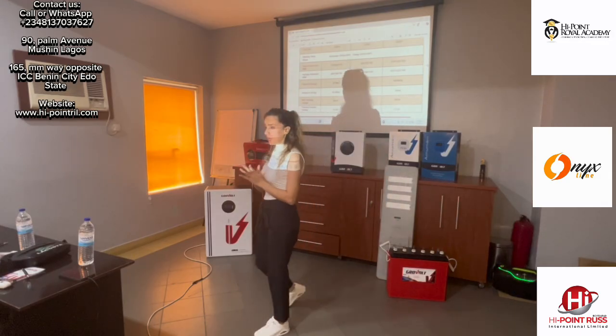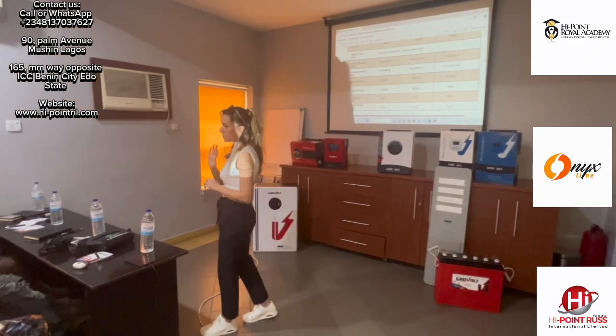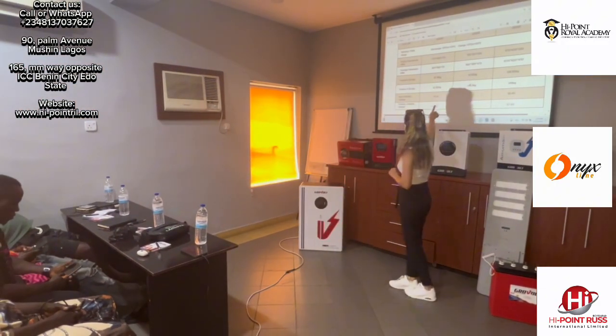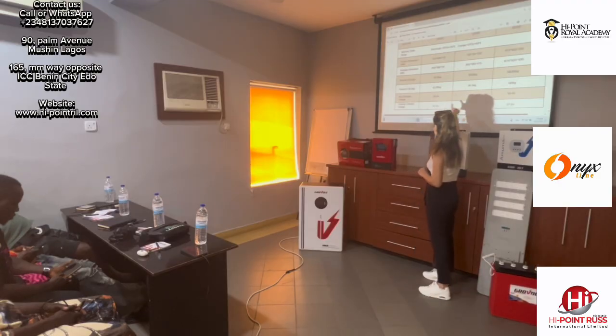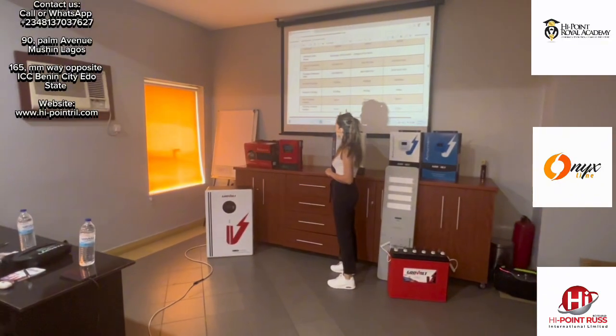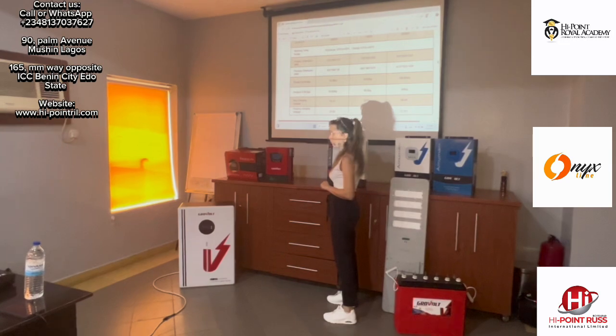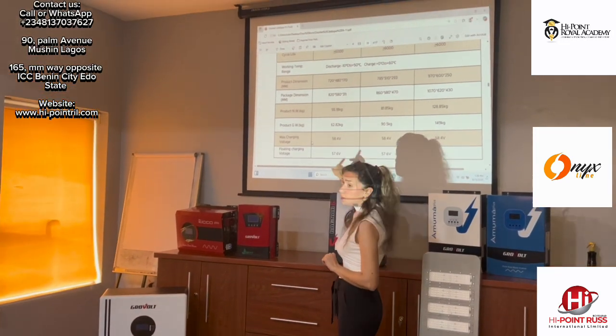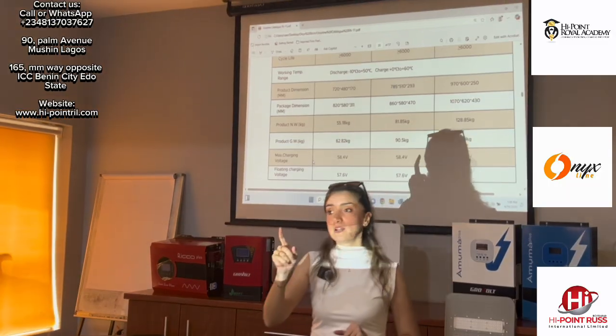When you connect your battery without BMS, you have to notice this value: the maximum charging voltage and the floating voltage. It's 57.6.